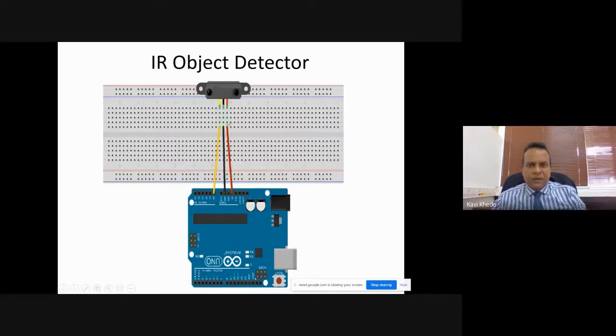So this is positive. And this one, the black one from the sensor, is plugged here. If we go down here, it is here. So this one is connected with this one, and this one on my microcontroller goes to ground. GND means ground. So this is negative, positive, negative. For you to form a circuit, you need to have a positive and a negative, the current and the ground. This is live, this is ground. So now my sensor is connected and has got power. This is to power the sensor. It needs to form a complete circuit with 5 volt and ground.